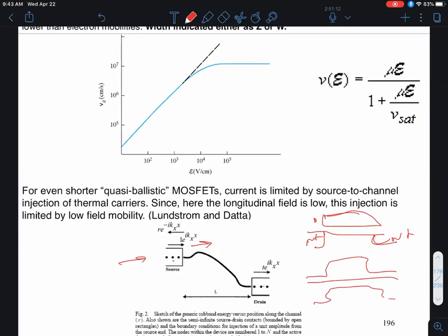Here I'm looking at it now, but now for increasing drain voltages. Well, if the drain voltage goes up, what's going to happen? The electron energies will keep reducing, right? That's what I'm showing in these figures, okay? So I have a high drain voltage, the source is grounded, and depending on the gate voltage, which I can show on this diagram, you can lower this energy barrier between the source and the channel, right?